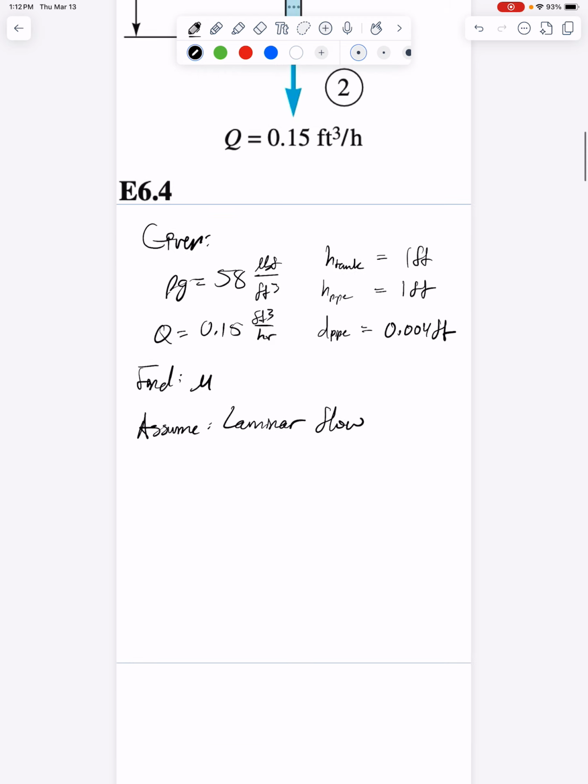So, what does it mean when I say laminar flow? A big part of that is that our h_f term gets simplified. Yes, Marvin. Why are we assuming laminar flow? Like I said, this is an executive decision I make now. There are key terms and details that I look at when I assume either laminar or turbulent, and they'll be more relevant in the next problem. But for now, I'm going to say laminar flow because I was not given enough information for Reynolds number for the time being.